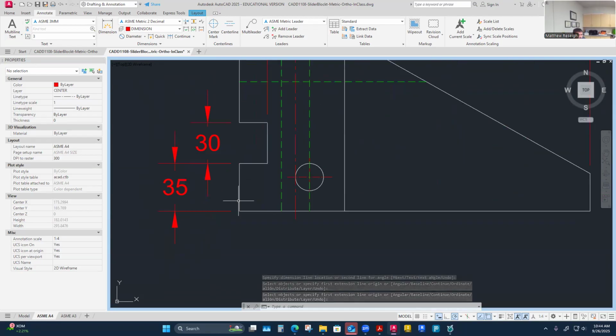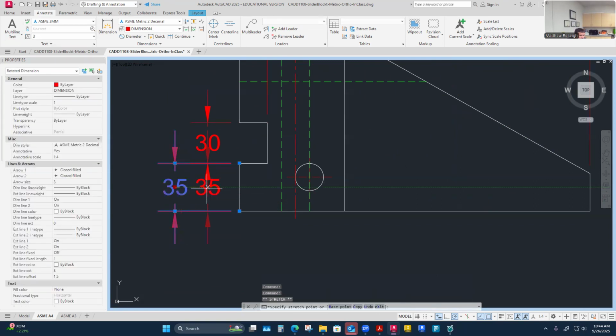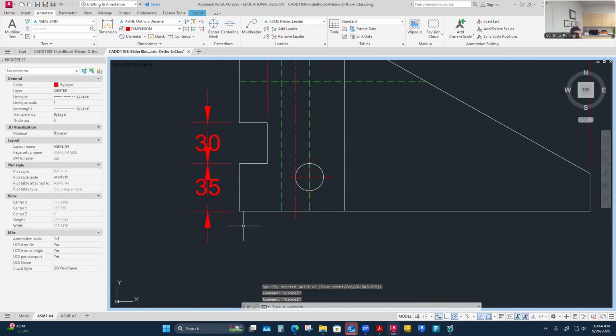And then I would argue, just start thinking down the road a little bit, what we have here is we start to have a stack up. These are called chain dimensioning. I lock in one point and then I lock in the other. That is starting to be down that chain dimensioning mentality, and why we kind of avoid chain.